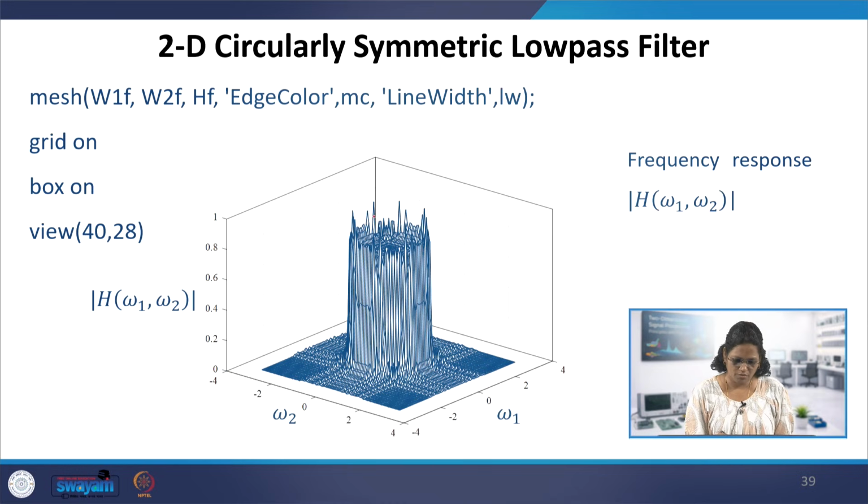Again, because of the number of samples, you can see that these plots have a very crude way of having the passband and the stopband. But we can have this circularly symmetric response in this low pass filter. These are the different ways of designing 2D FIR filters. One is the frequency sampling method, and first we had seen different types of designing the 2D FIR filter using the window method. Also the frequency transformation method we will do through the demonstrations.